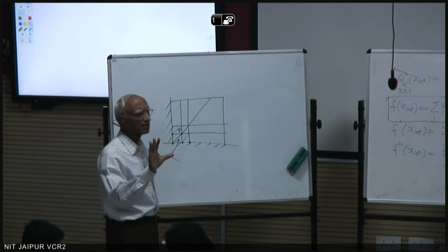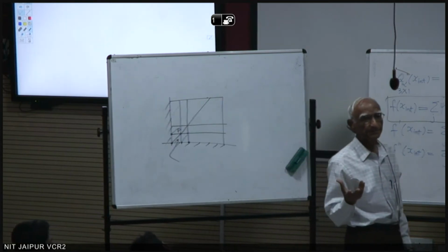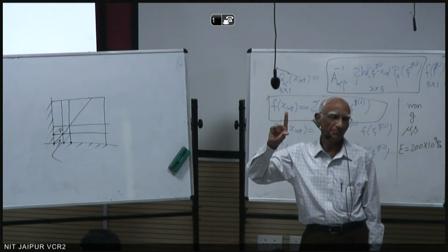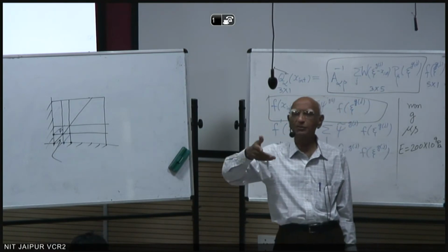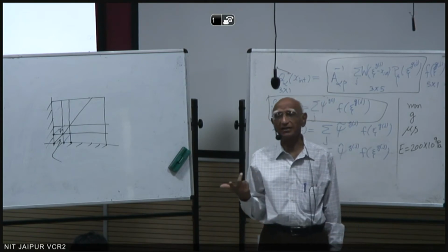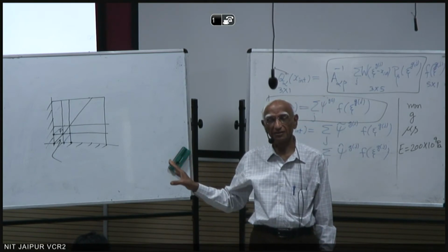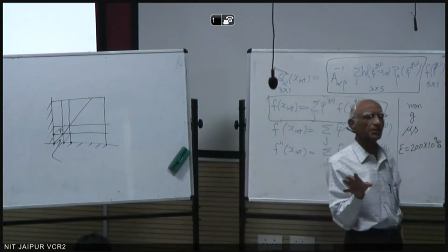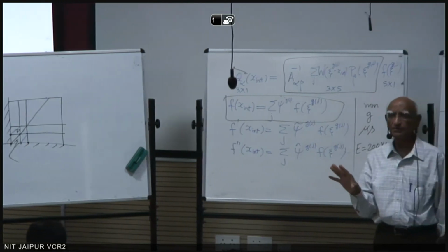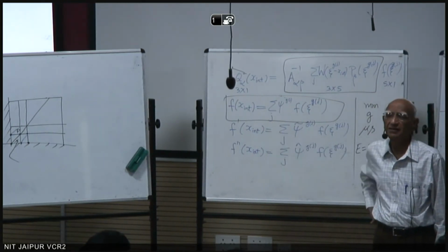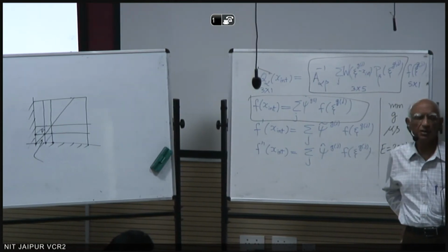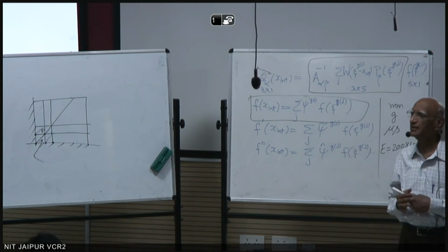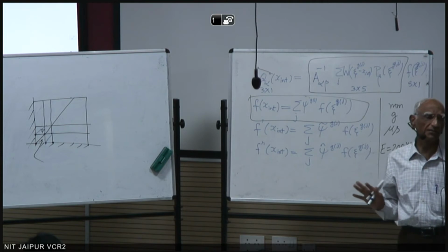Same thing happens if you are doing a plate problem or a beam problem. We say thickness cannot change, right? Because that's in Euler-Bernoulli beam theory. Thickness doesn't change. So that's a constraint, and that can cause problems too. So whenever you have a constraint, whether you have a large deformation problem or a small deformation problem, mesh design can give you erroneous results. Erroneous means wrong results. So we have to be careful. That's all one can say.